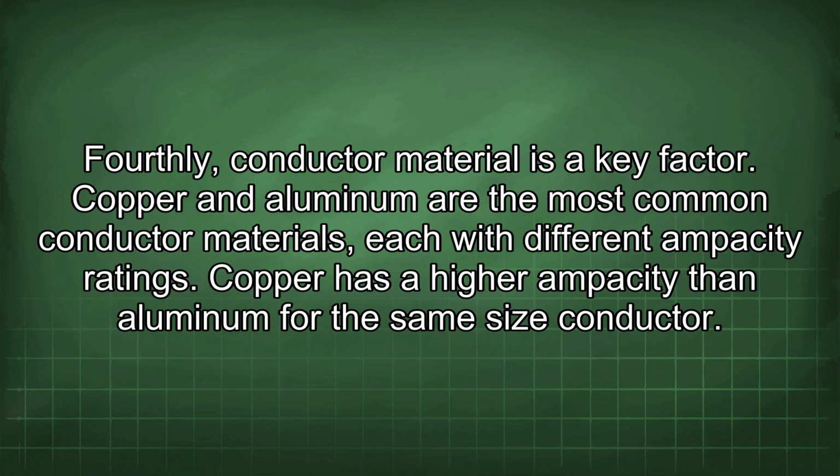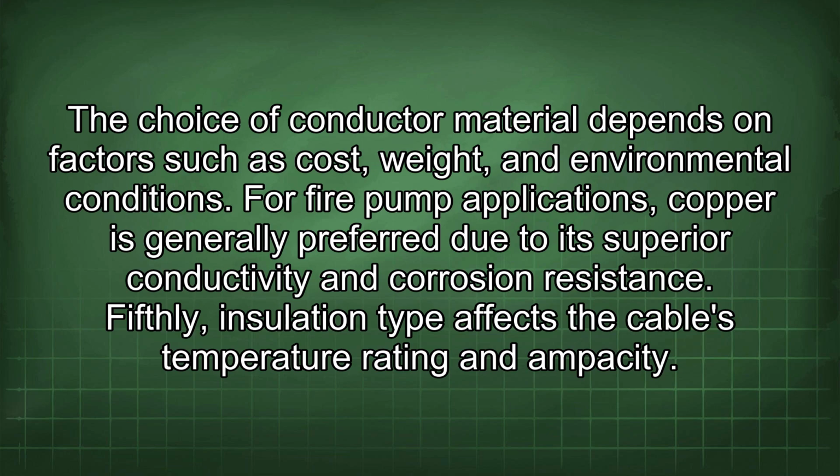Fourthly, conductor material is a key factor. Copper and aluminum are the most common conductor materials, each with different ampacity ratings. Copper has a higher ampacity than aluminum for the same size conductor. The choice of conductor material depends on factors such as cost, weight, and environmental conditions. For fire pump applications, copper is generally preferred due to its superior conductivity and corrosion resistance.